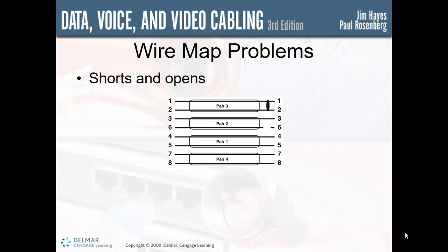Next thing I want to discuss will be problems that you may run into. In most wire map problems occur at the connections themselves. Typically, physical examination of the connections should find the fault. Wire map errors fall into several basic categories. One would be a short or an open. Now, a short occurs when two conductors are accidentally connected, and an open is where one or more wires are not connected to the pins on the plug or perhaps at the jack.